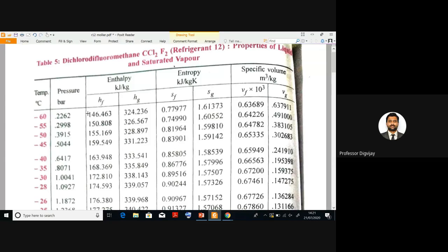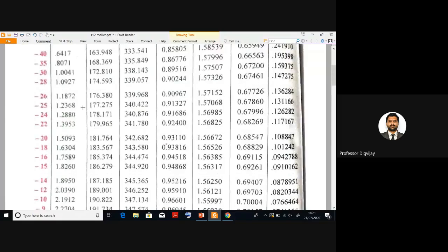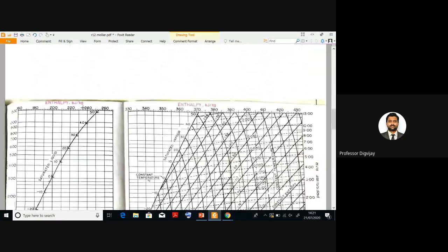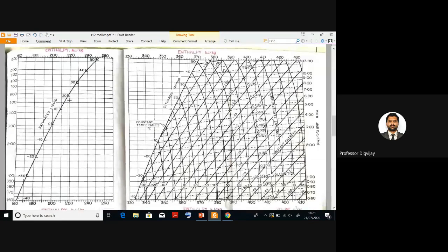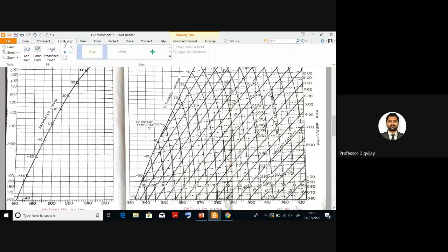So this is similar to what we had as steam tables in your second year of engineering. In that, you used the steam tables and calculated the enthalpy values. Then you might have calculated the X value. X stands for dryness fraction. So whenever you are under this diagram, between saturated liquid and saturated vapor, you get that.